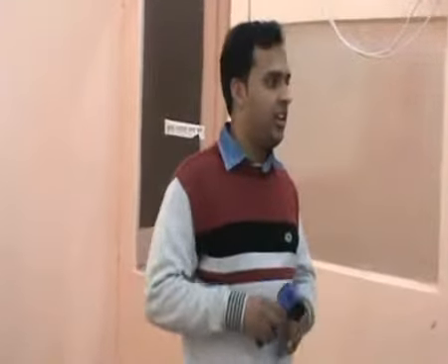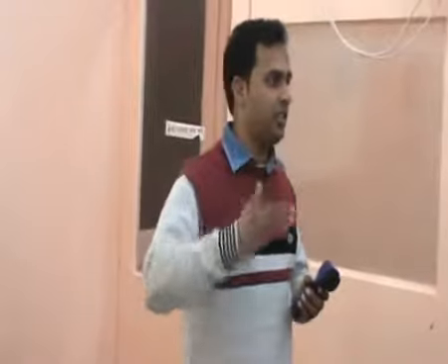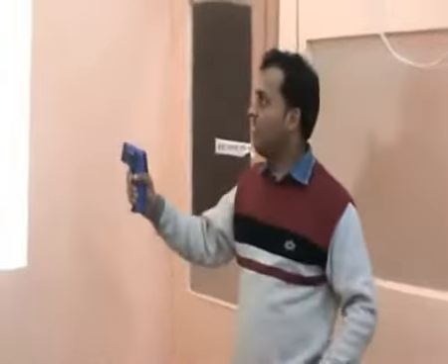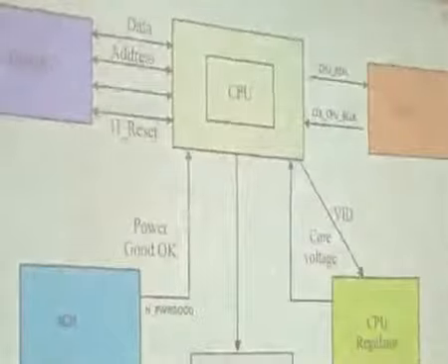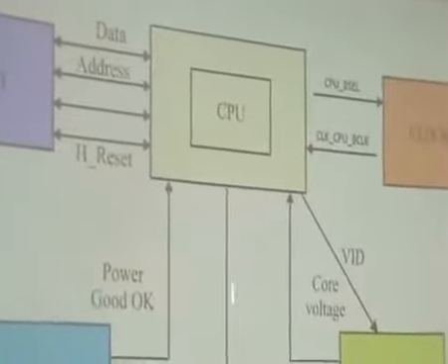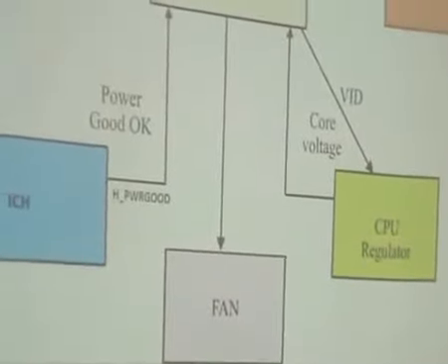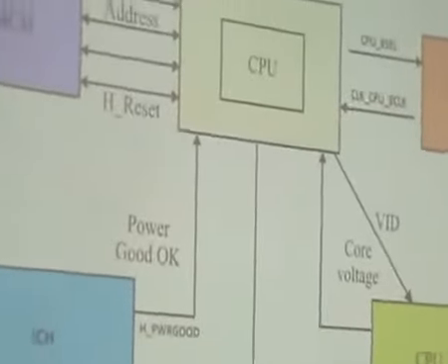This is ACPI, Advanced Configuration Power Interface. Why was it launched? So that your motherboard does not get burned in an extreme case. The voltage is flowed in sequence. We call this ACPI, so as to save energy, not to power on everything at one time. So we'll see how this core voltage is generated. After it gets the core voltage, the CPU will send a signal to the fan controller, also called the hardware monitor controller. There are two terms: fan controller and hardware monitor controller.